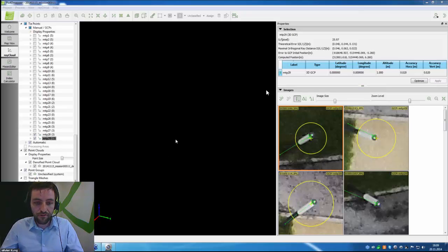What's the minimum number of passes? For example, if you have several straight miles of right of way, would 2 passes be sufficient? Actually, in theory, 1 pass is enough. However, with 1 pass, you have the risk that you start having error accumulation and the accuracy will not be preserved. So when you need to have a straight line, we recommend always doing at least 2 passes. And anyway, you usually need to get your drone back, so that's a good thing to do. So 2 passes would normally be sufficient, but if you can do more, that's even better.